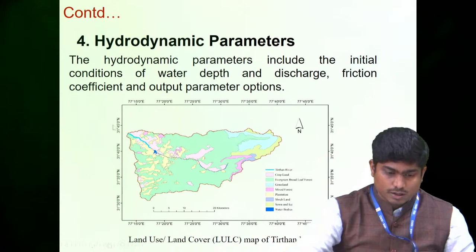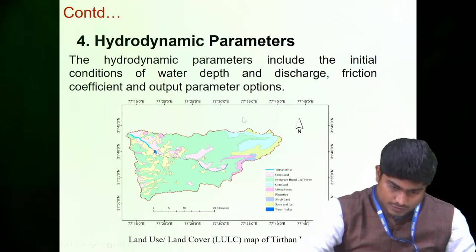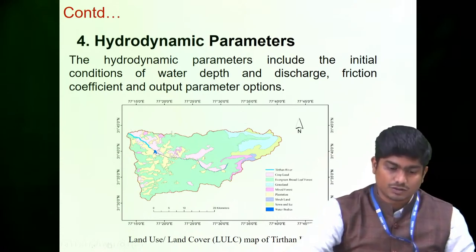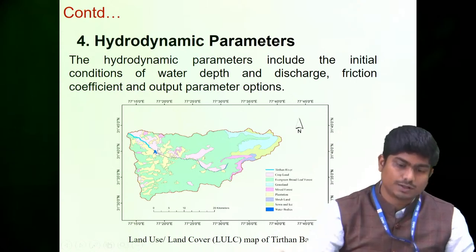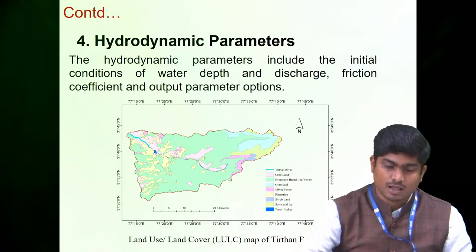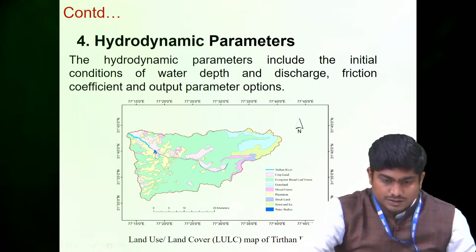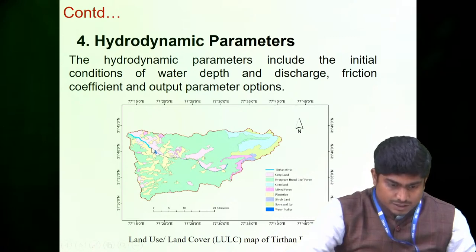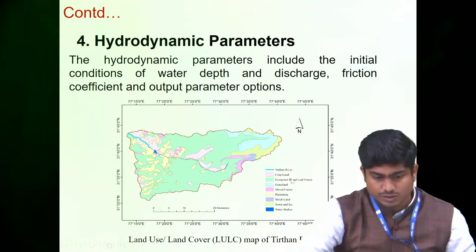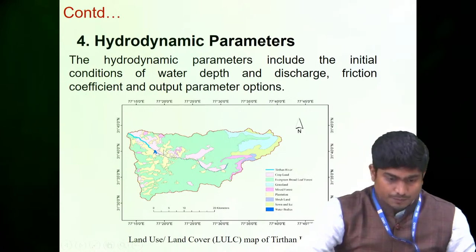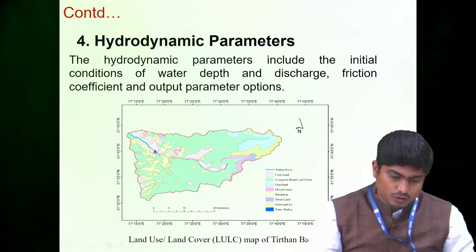Now, ideally you should have this land use land cover, and then for the corresponding class you give the different Manning's n. But if you look at this, this is the typical land use land cover that I have, and my stretch is around 9 kilometers. This 9 kilometer stretch is falling into only one class, cropland. But it is not true, because this is only a 9 kilometer stretch.